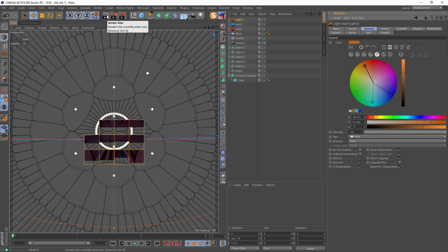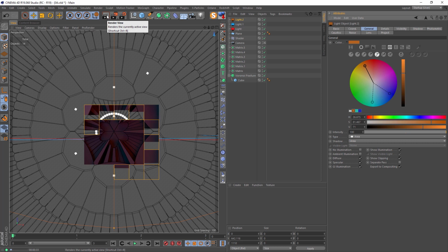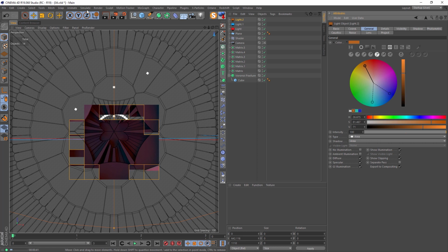The higher the speed of your CPU, the faster the render will be, and global illumination takes a lot of time to calculate. You can check your image without global illumination. Sometimes you don't need this effect and you will get a very huge speed increase. So you'll see we have 40 seconds and we see a small part.